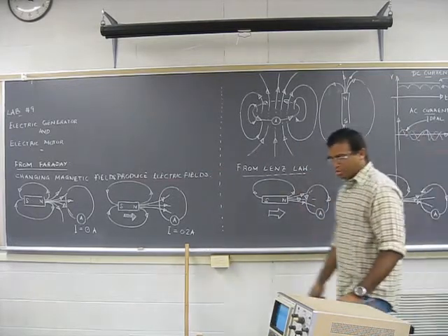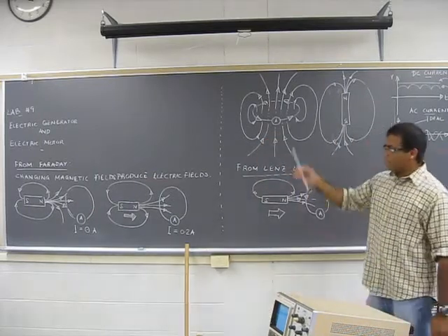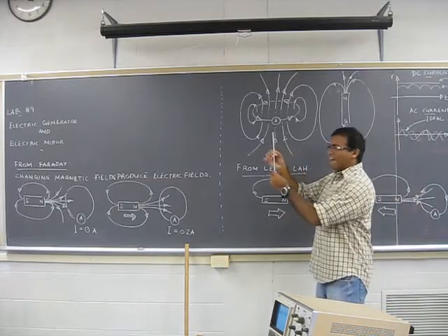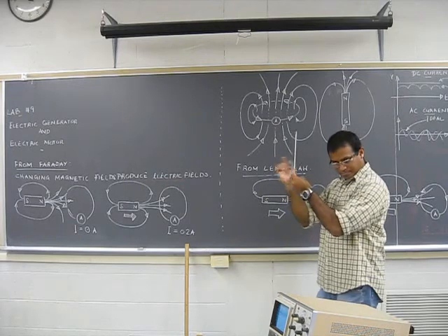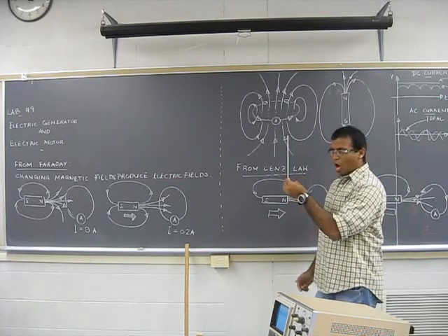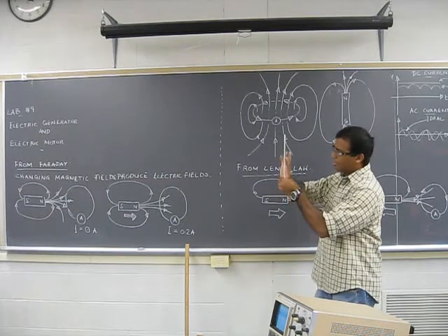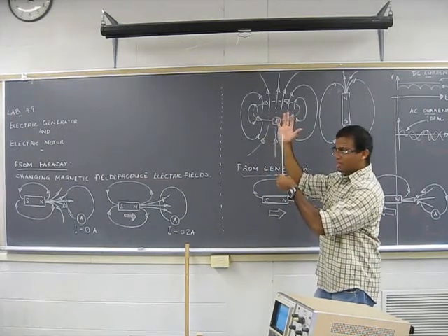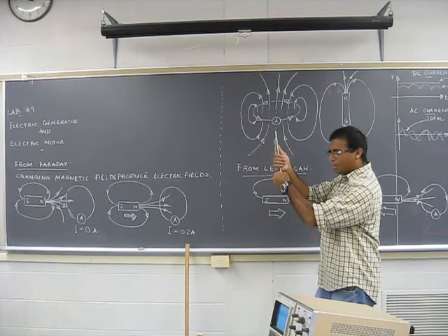Now, another thing that I want to say, you may have gone through this, let's refresh. If I have a conductive wire like this, okay? Every conductive wire will have a magnetic field around it. Okay? So how do you find the field? If we know the direction of the current, let's say the direction of the current is going up, I take my right hand, put my thumb to the direction of the current, curve my fingers around.